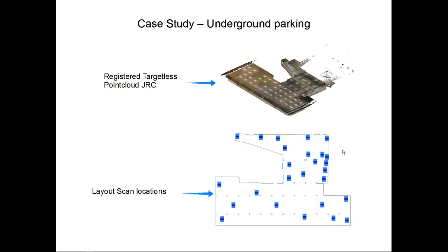But in normal ways, we would have probably taken only 1 scan position over there. Because we don't use targets, we had the freedom to take 4 individual scan positions with lower resolution, because more doesn't always mean better. In our case, having a better distributed point cloud along the length of an area of interest is better than having 1 scan position from 1 viewpoint gathering that information.